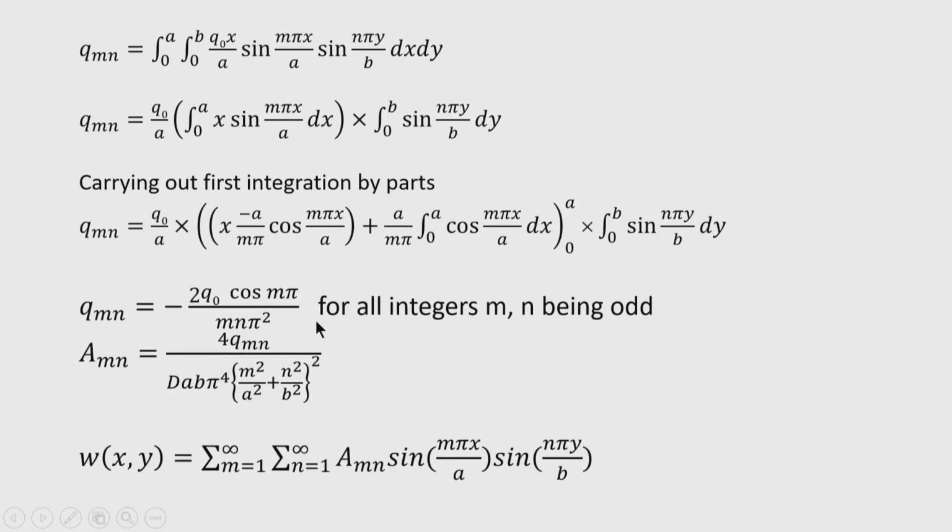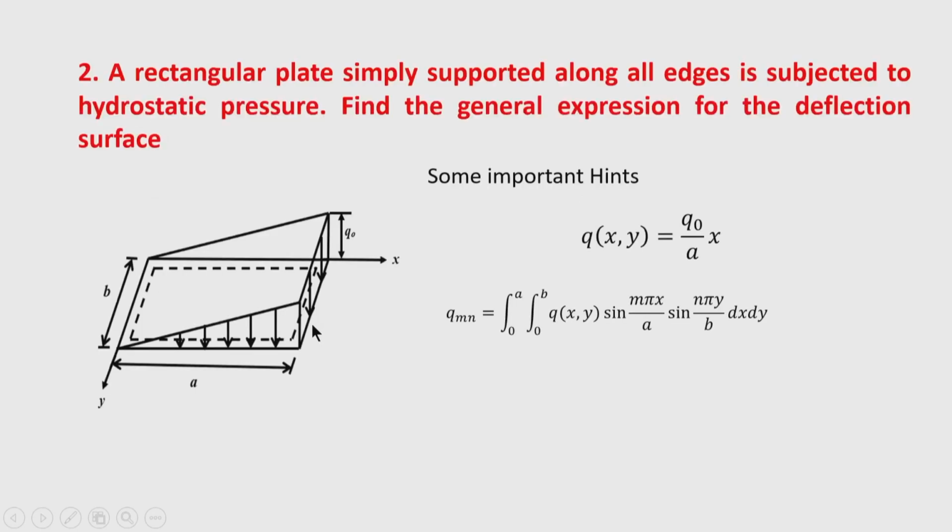So, what we have done in today's class is we have illustrated the problem of plate on elastic foundation. Then I have discussed a special problem where a triangular shaped plate is taken, the plate is equilateral and subjected to moment along the edges. This moment, of course, the magnitude is taken equal and it is symmetrical, that it is trying to sag the plate. So, under the action of this edge moment, we have found the deflected surface of the triangular plate, and from that we have found the expression for bending moment and twisting moment.